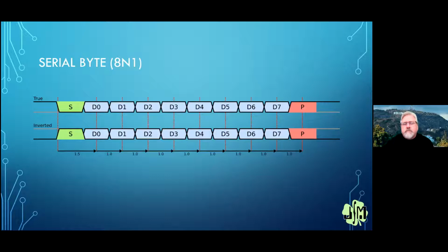And remember, the DMX spec has been around a while. I'm sure that things would work fine without it, but it does use 11 bits. Now, again, here's the inverted mode. That's just an electrical inversion. I just talked about transmitting. Before we get into code, I made a note down here. You'll see this says 1.5, 1, 1, 1, 1. These are bit periods. So when we're a receiver, what we are going to do is watch for this.